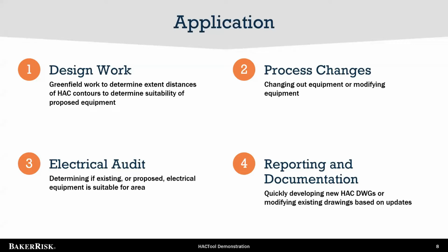So if you're working on a greenfield study, maybe you have a few different layouts of a unit that you're looking to build, a few different plot plans, and you want to know, hey, what is the classified area using that point source approach boundaries for the different equipment in the facility and based on the different plot plan layouts. HACTool gives you the ability to move and shift things around, to really build these custom units and to quickly calculate an overall view of the classified area that you're working with. So really useful for design work, and BakerRisk has been involved in numerous greenfield studies related to that.